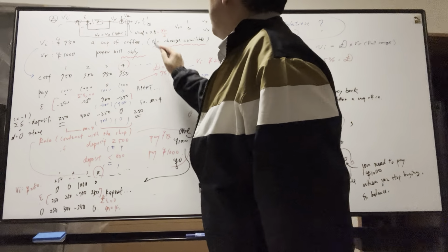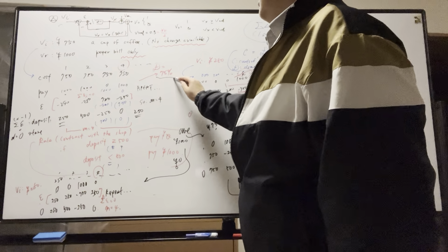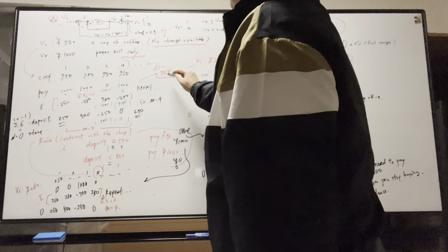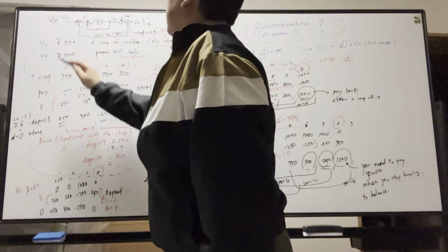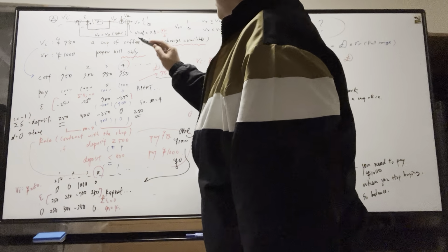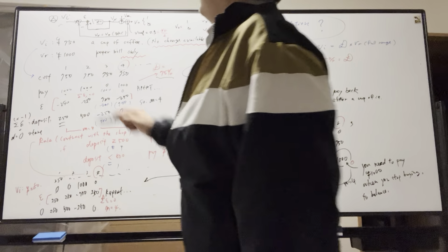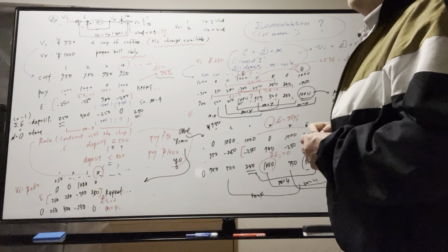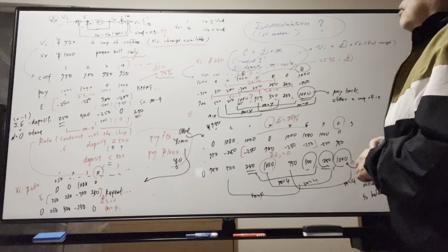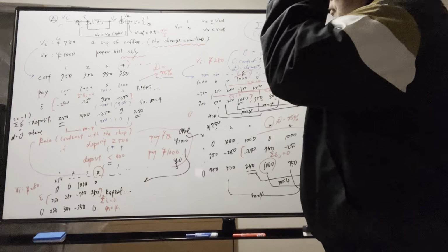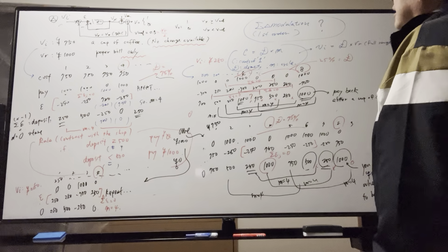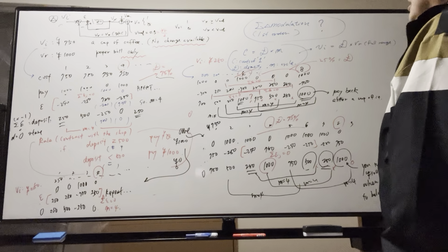So the density of bit 1 is 75% here, and 0.75 times the full range of 1,000 makes 750 yen. So you can estimate exactly the same value as the input, the cost of a cup of coffee. So this is sigma delta modulation.